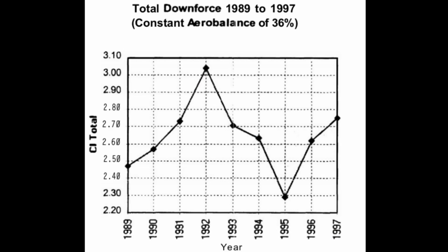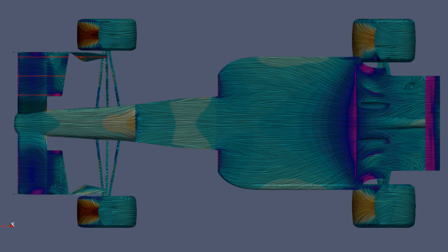Lastly, the downforce distribution the paper was using is 36%, which is basically the same. I was getting 3,118 newton meters about the rear wheels, with the wheelbase being 2.92 meters.